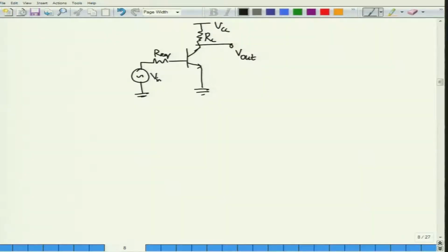Okay. So, for a simple BJT amplifier like this, you do not really worry about impedance mismatch. In fact, what you want is, in order to maximize the voltage delivered to the circuit at the output, you do not even aim for maximum power, you aim for maximum voltage, right. So, if I replace this transistor with its equivalent circuit with a little bit of an idealization, then I know the condition that I need to have in order to maximize.